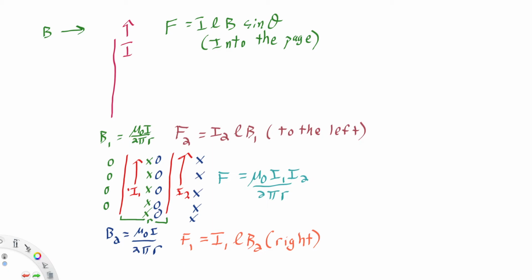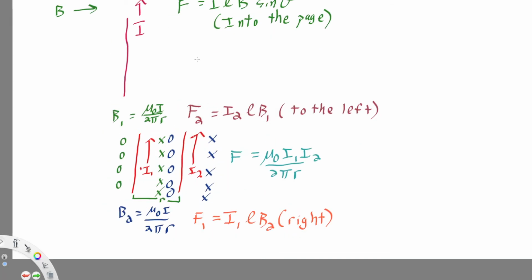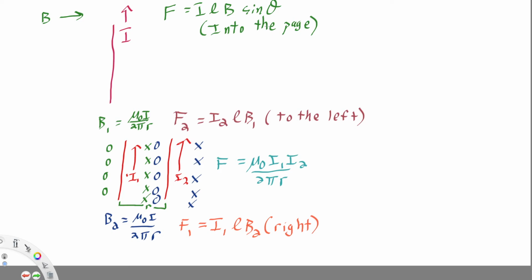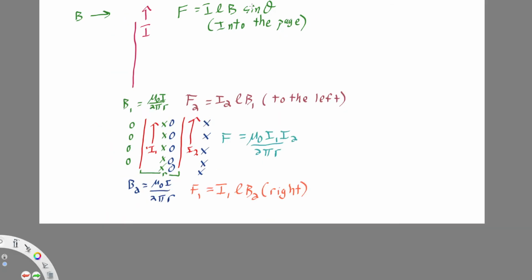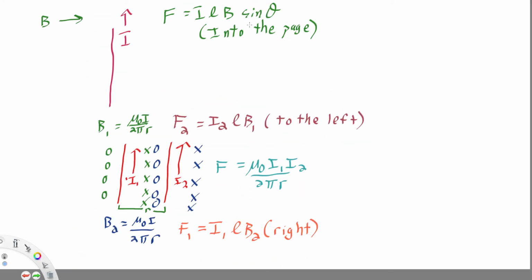So the little tiny wires on the processing chip actually feel the B field of nearby wires quite strongly. And that doesn't mess with them at all? It absolutely messes with them. That's not the primary reason, but it's a big reason why your processor wears out. So processing chips don't last forever, and this is one of the reasons why.